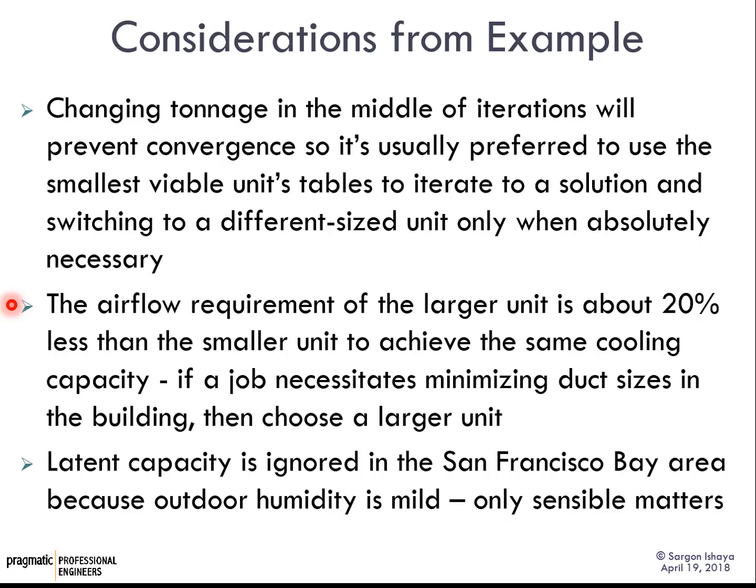Second consideration, the airflow requirement of the larger unit is 20% less than the smaller unit to achieve the same cooling capacity. So if your job necessitates minimizing duct sizes, then you would choose a larger unit. And note how we have ignored the latent capacity.